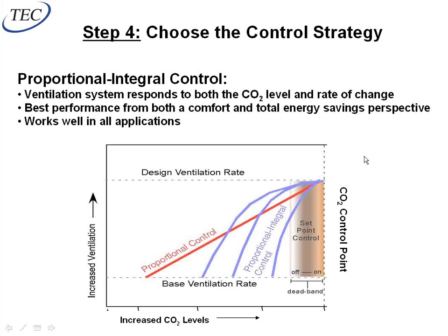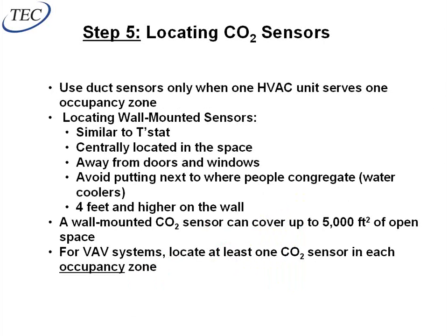So I get more of a curve pattern that gets me closer to my reality here. It's just a better way to do it. Where do I put the CO2 sensors? That is a very common question. And like I said, the first thing is I like to put a CO2 sensor everywhere that I need to have control. So if I decided that it was a good idea to put a temperature sensor or a thermostat in a particular space, that's probably the same space I want to put a CO2 sensor in.